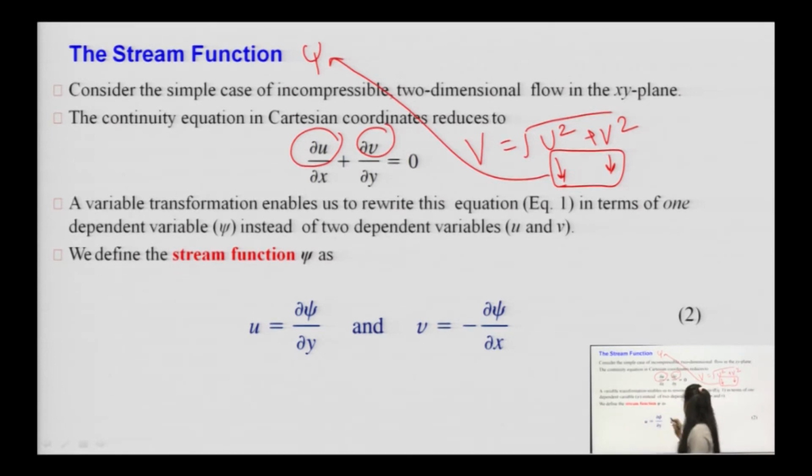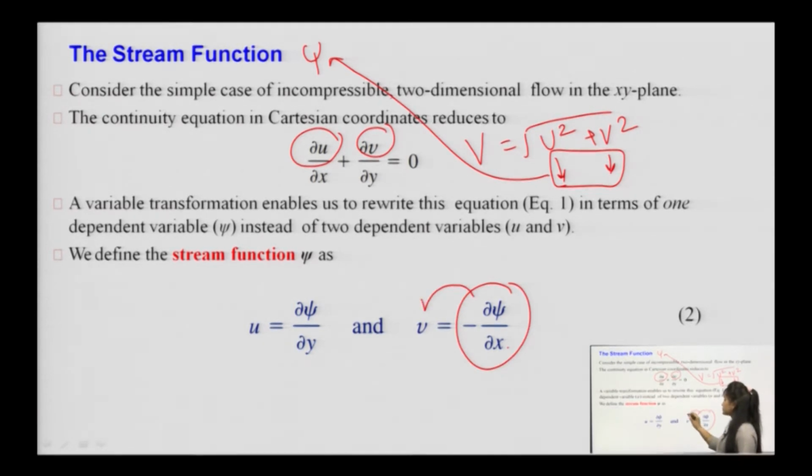Like if we take the partial derivative of psi along the x axis, the velocity component we get is at 90 degrees, and that is the v component, and if we take the partial derivative in the y direction, then the velocity component we get is the u component. Now, the question comes: why does this particular stream function exist, and how does it exist? What is the assurance that its role is vital, or that it exists while the fluid is flowing?